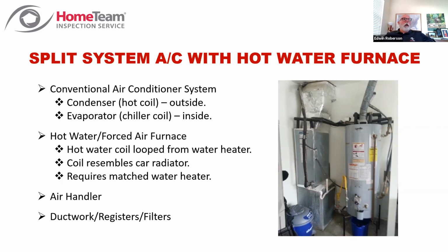Like I said, these systems seem to last a long time. And really, if your water chemistry is good, there's really nothing to mess them up, because what would mess these up as much as anything is scaling or buildup inside the pipe that might hurt the heat transfer. But we see them; they heat well. They really don't make them anymore, but you'll see one sooner or later. Now you'll kind of understand better what you're looking at.